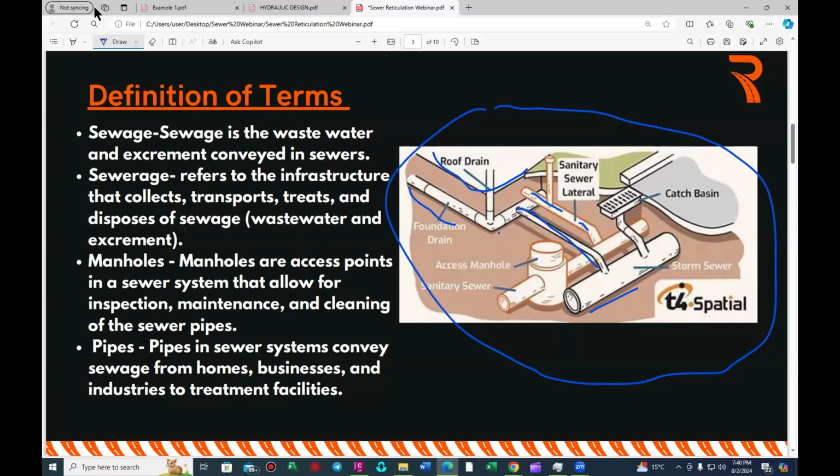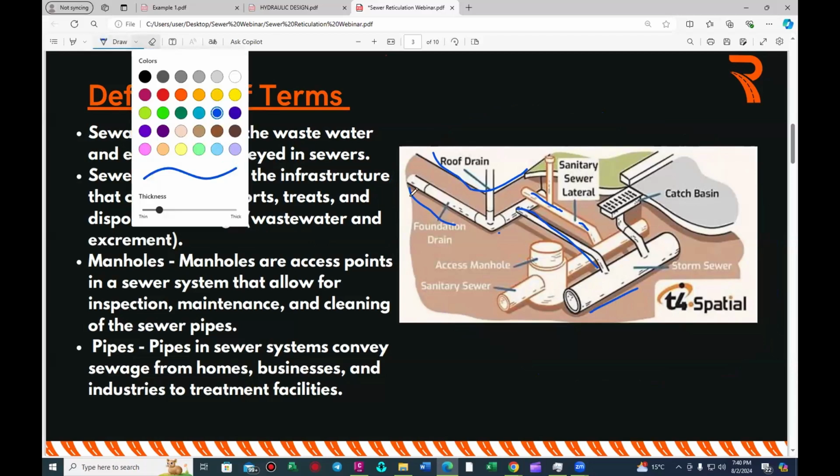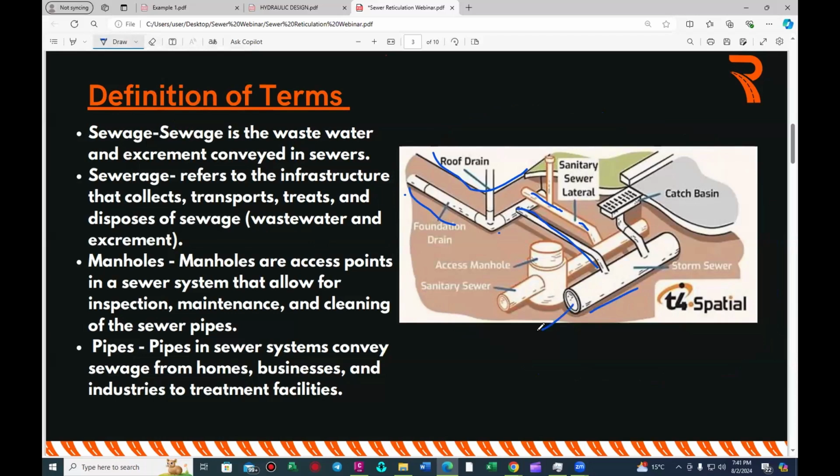So one thing that you guys have to understand is that there is what we call sanitary sewer and storm sewer. Those are two different things, right? As you can see from the words, there's a storm sewer. The storm sewer collects your storm water, right? This is the water due to the rainfall. When it rains, water that's collected by your catch basins, water that collects on the side drains of your roads is collected by your storm sewers. Even the gutters for your house have down pipes that pour into side drains, that then pour into these pipes that pour into your storm sewers.